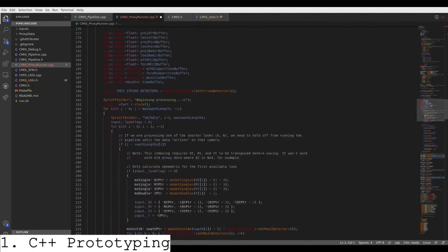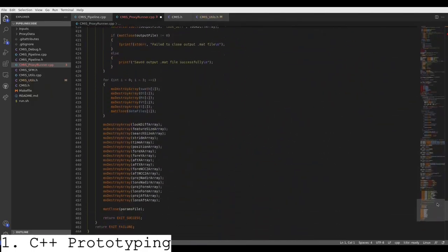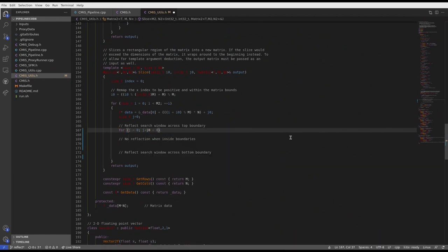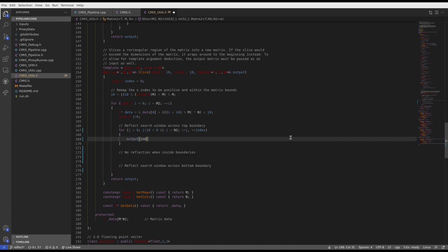First, make a prototype for your science algorithms in C++. This will provide a framework for the structure of your HLS code and will serve as a baseline to compare HLS results to. Here you can take full advantage of C++ constructs like dynamically allocated data structures, because this code will not be run on the FPGA.